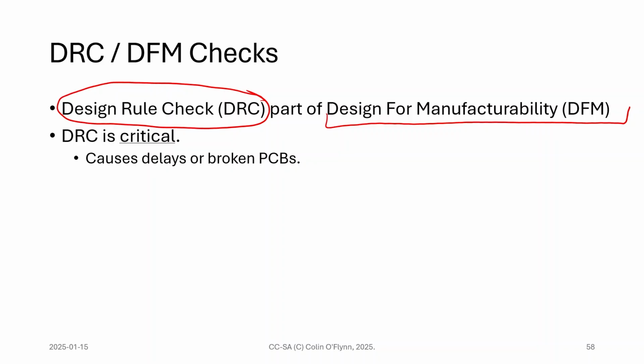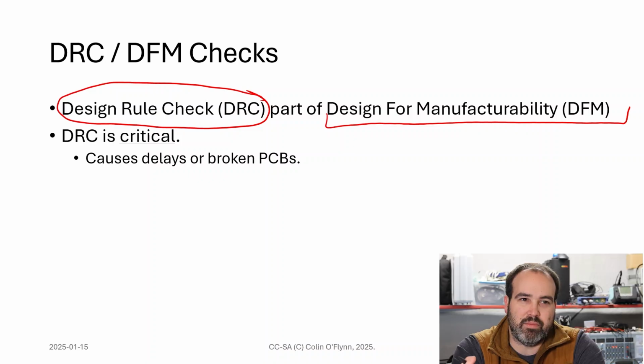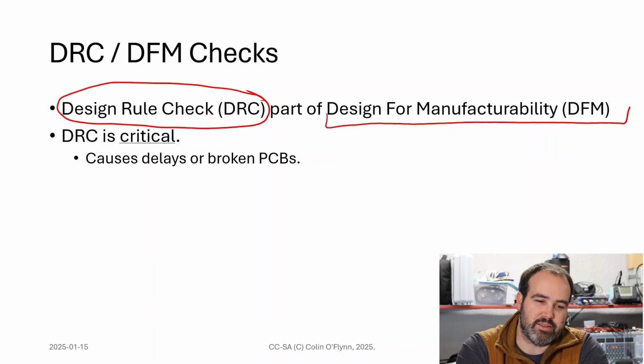But for PCB design, most of the time when people are talking about DFM, for really simple boards, what we mean is that the boards get made correctly. If you're doing even small amounts of automated assembly, you also want to look at how you increase the yield or likelihood that you're going to have successful boards after the PCBs are assembled into PCBAs.